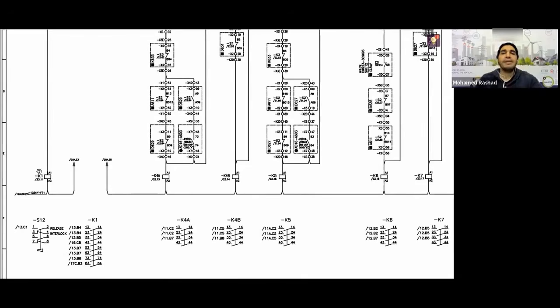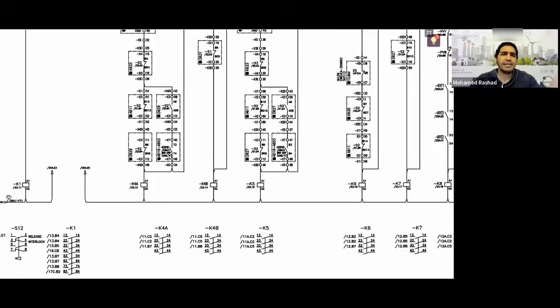What does interlock bypassing mean? It means you might have interlock circuits that are indeed complete, but you have some issue, for example, in the electrical circuit. Of course, if the electrical circuit is not complete, it won't allow you to execute a close or open command for any command you have. Therefore, if you are sure that the interlock circuit is indeed fulfilled, for example, you are sure that this is a closed name, or whatever you saw physically or with your own eyes and are certain of it, you can do something called interlock bypass. This will overlook any circuit related to interlocking and will immediately allow the closing or opening of any command you want. Okay, that's not what I'm going to focus on.